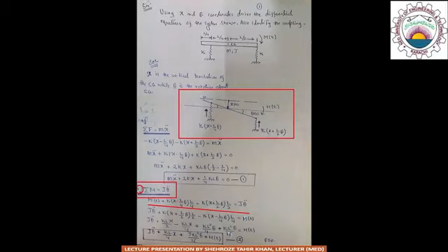Like the previous equation, in this equation we also take out stiffness element k as a common factor. Here kx is the force produced by the stiffness element in the vertical direction, and k into L by 4 theta is the force of the stiffness element when it tends to turn the rigid bar about its center of gravity, thus producing an arc length S = r theta.